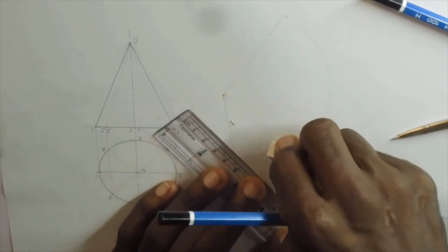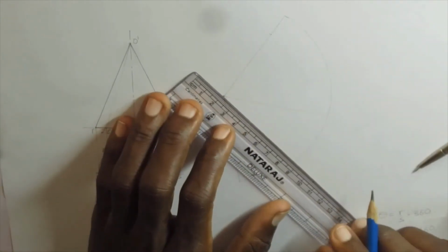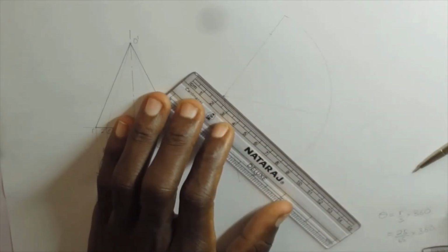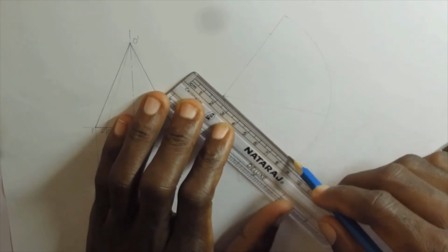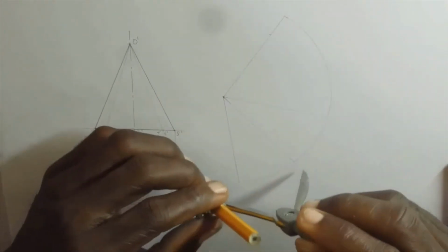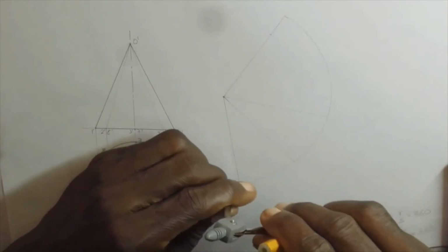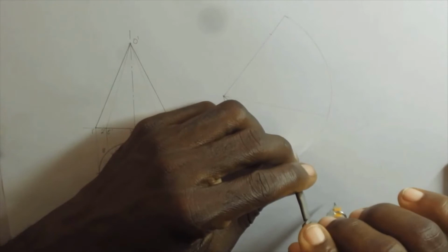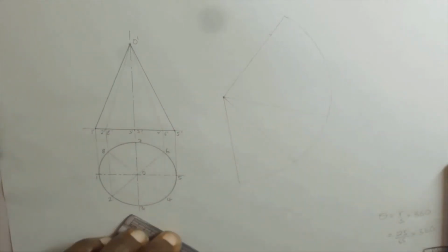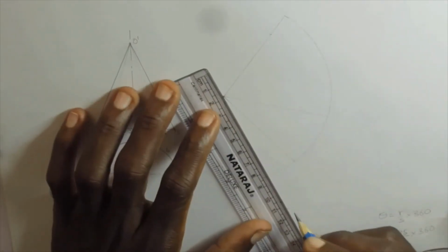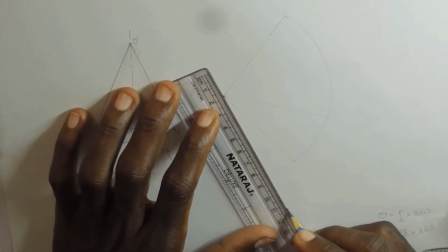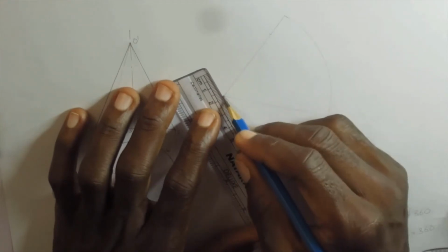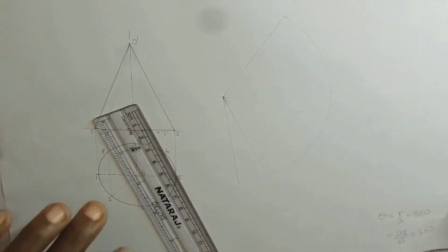So when you do that, you will then draw another line from the center of the arc to the circumference of the arc that way. Then you do another bisection of the next one, the next angle again. Then you have a smaller division there. So you draw another one. So this gives us the actual size that we'll obtain in case we divide this arc into 8.